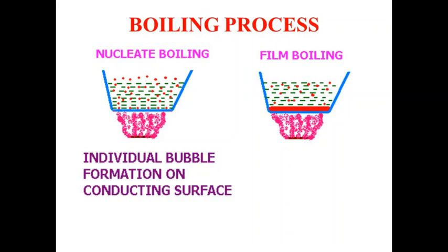In this way, gradually the entire fluid in the container attains the saturation temperature, and after that whatever excess heat is received adds up to the latent heat of vaporization, and gradually we find more and more tiny bubbles coming up, like nuclei, and they are coming up from the top and collapsing together, and gradually, as if from the top of the surface, they are flashing into steam.